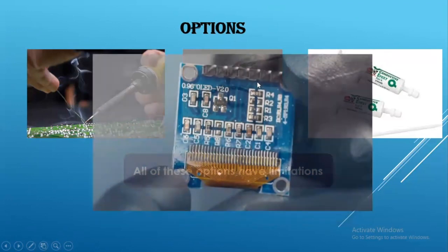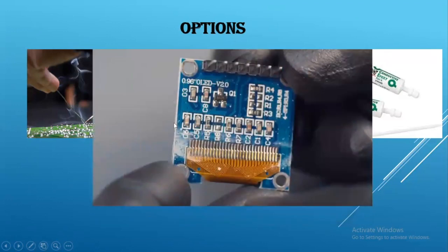And if we think about a PCB board, the connections which we make to the PCB board can be soldered because we have enough space. But when we see this ribbon strip, which has conducting films or lines, and this side is going to the LCD panel, it is very thin, and we cannot use the conventional soldering method because it's plastic. We cannot solder it, and the lines are so close-packed that we cannot use silver paste either.